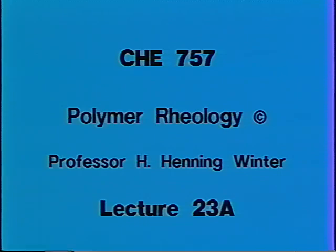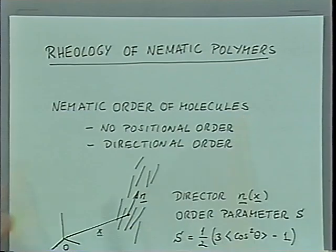Winter Lecture 23A. Liquid crystal polymers have a very interesting rheological behavior, and that mostly comes through the self-ordering of the molecules, which by itself then is caused by the molecular structure. Let's talk about the structuring and the order of those liquid crystals before we discuss rheology by itself. And I want to concentrate on nematic polymeric systems, which have a special type of order.